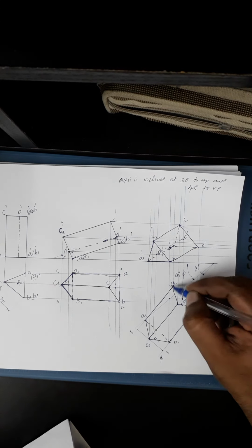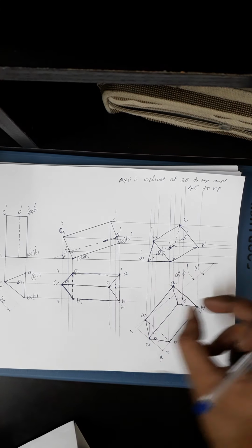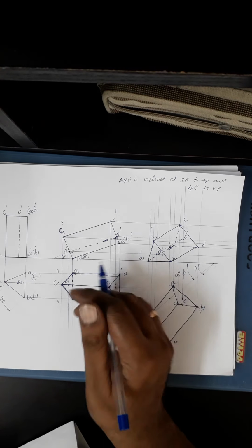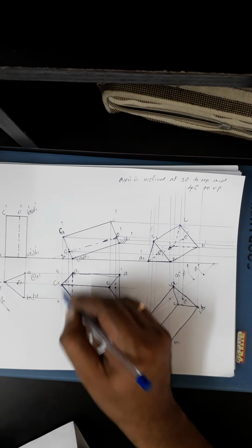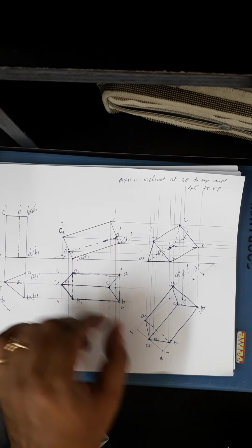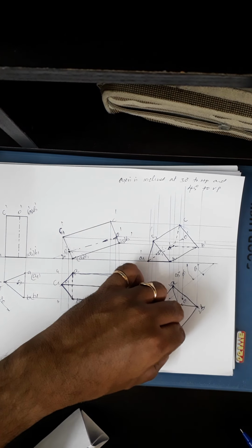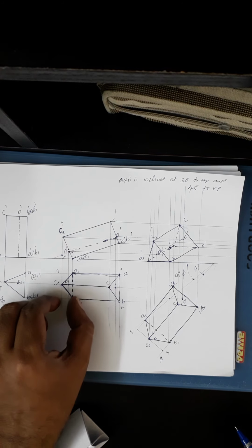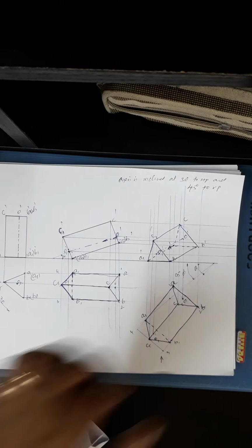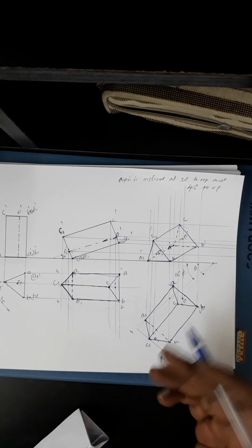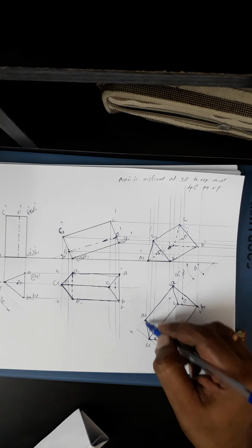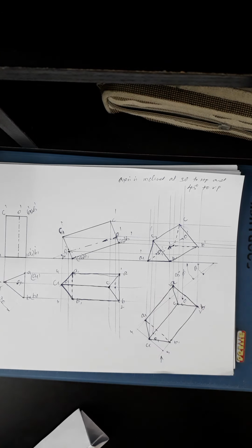Then A, B is on 1 and 2. C is at this distance on this line, so from this 1, 2, I'll take that distance and mark that point as C. Then C1 is on this 3, 4, right? Exactly at the axis line. Then 4 to A1 I can take and transfer here. 4 to A1 is same as 3 to B1, right? So I can transfer and get the other two points. See, it's easy for me to redraw the same view here. It's looking different, but when you draw neatly, you can get that view. So same view. This side is visible, the outermost edges are visible, and this is the total same thing you draw.